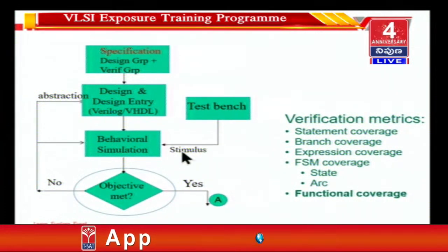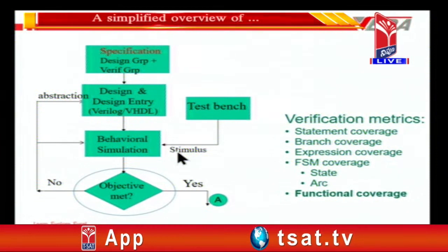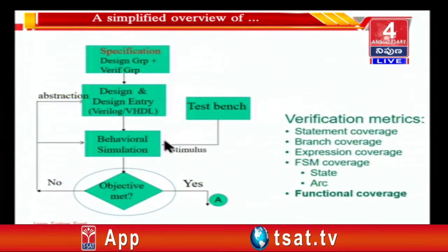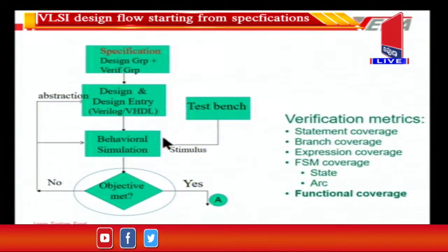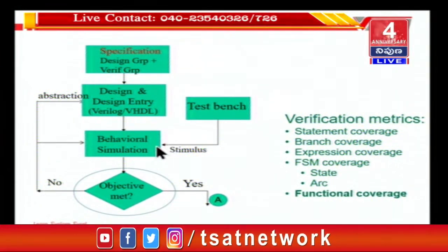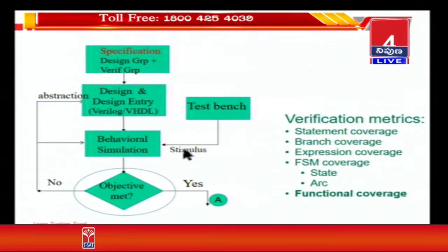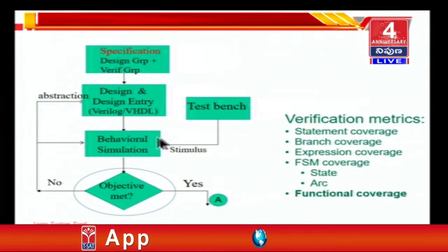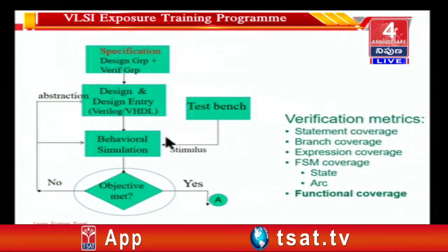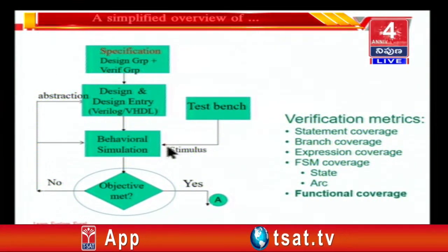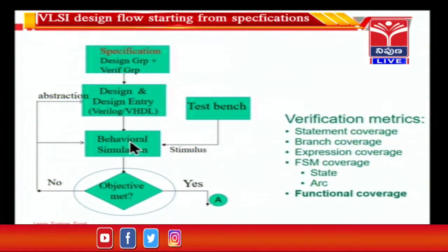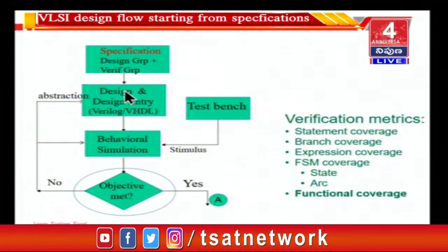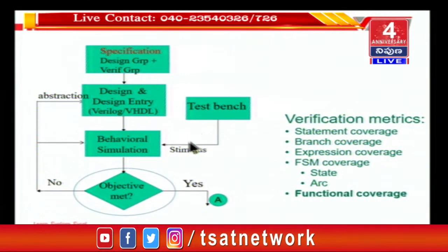And stimulus means applying the inputs, exercising the design with different types of data, with different types of scenarios, combinations of data and address, if this happens to be some kind of a processor or whatever it is, or some control inputs, combination of control inputs, all possible and allowable and valid combinations of inputs are given from the test bench to the behavioral simulation, which takes in a design code, it takes in a test bench.